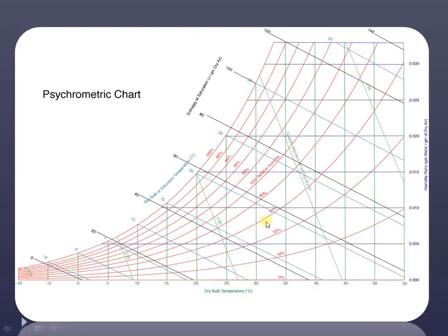Now we know that psychrometry is the branch which deals with determining the thermal properties of moist air. The various thermodynamic properties of moist air are dry bulb temperature, as we have seen earlier, then specific humidity or humidity ratio. Dry bulb temperature is nothing but the temperature of the air measured by an ordinary thermometer. Humidity ratio is the amount of water vapor present per kg of dry air. Now let us see how to determine all those properties if we know any point on the psychrometric chart.